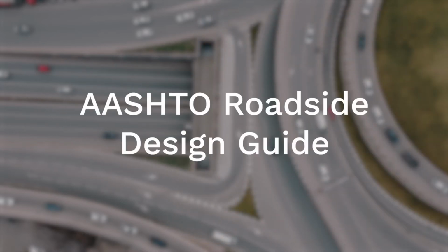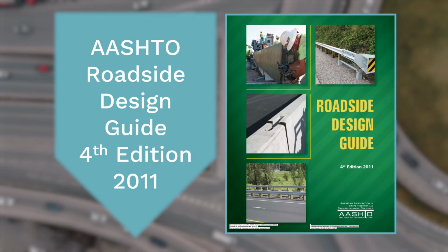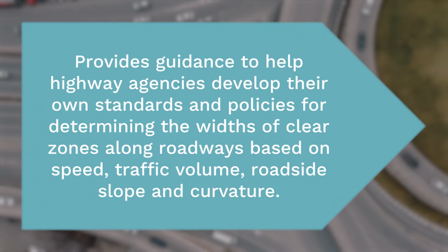Today we're going to be discussing clear zones. The AASHTO Roadside Design Guide is the reason for this meeting today. The current AASHTO Roadside Design Guide is the 4th edition, published in 2011. This document gives us guidance to help highway agencies develop our own standards for determining the widths of clear zones. These are based on speed, traffic volume, roadside slope, and curvature.